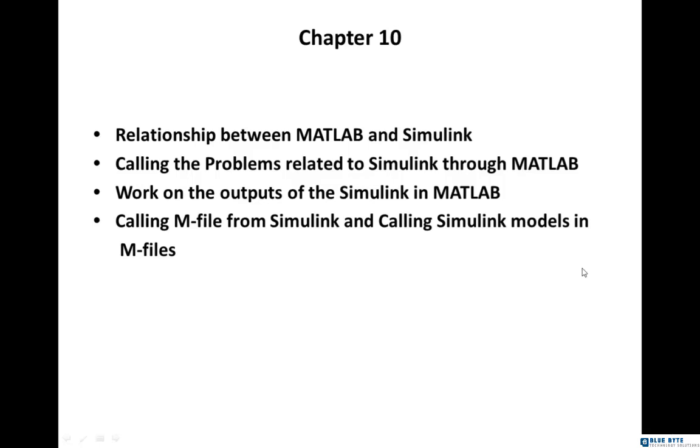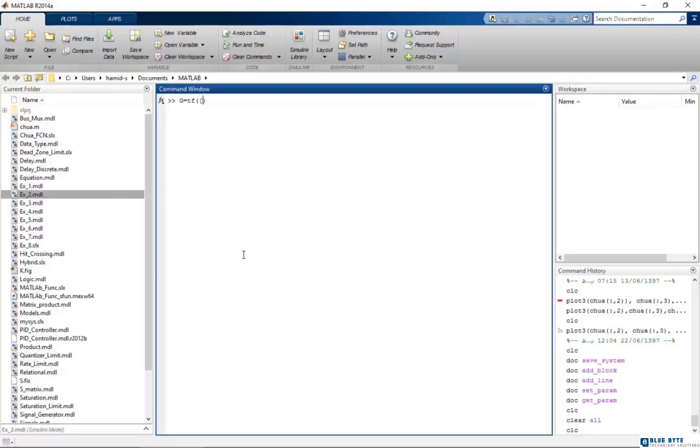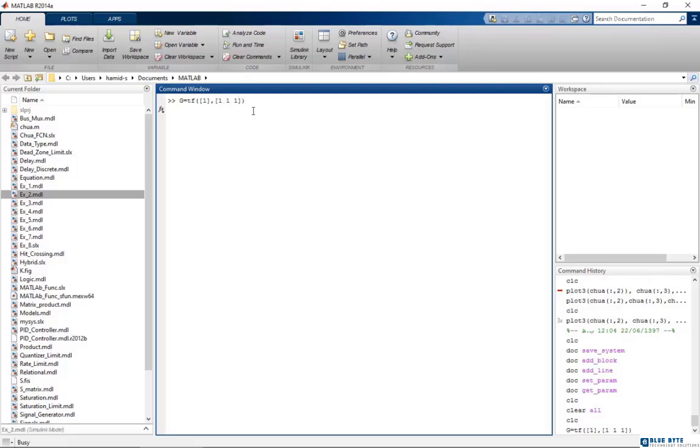If you remember the multiple simulations of systems, we simulated some systems using SS, TF functions, etc. Again, here I want to review how we can use the MATLAB code environment in order to enter data in Simulink. Suppose that I want to define a transfer function using TF code. Its numerator is 1 and the denominator is s^2 + s + 1.